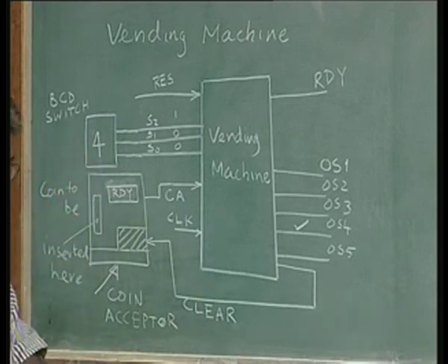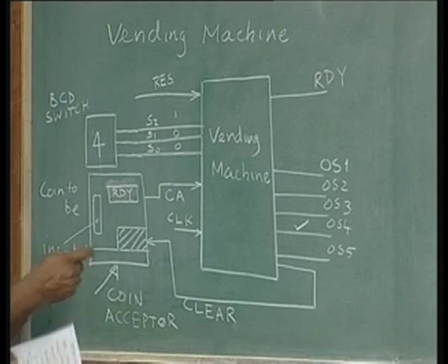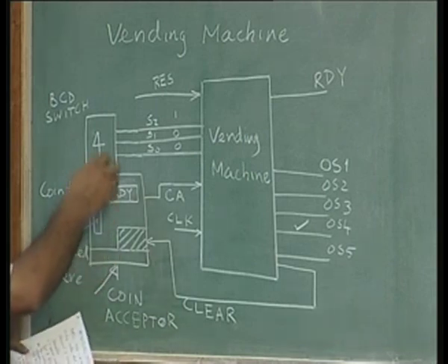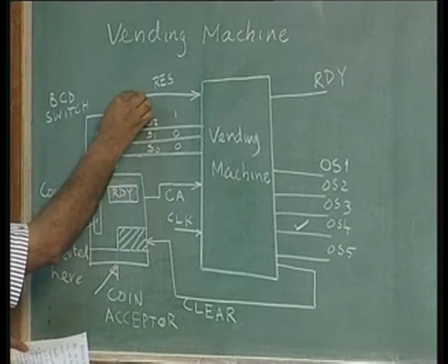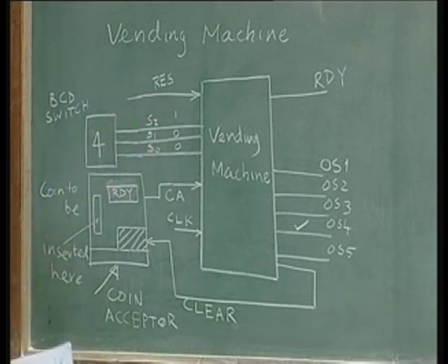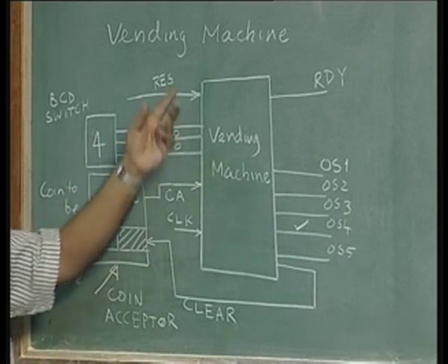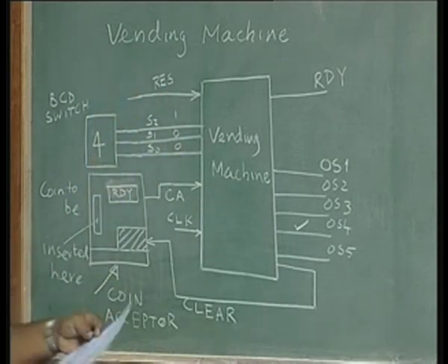And all reset can be done in different ways. You can have a reset by a switch button. You might have seen this by a simple switch. I am not going to talk about this in microprocessor circuitry. You know how to do a reset. Power on reset, we can have a simple RC circuit which can do this job.